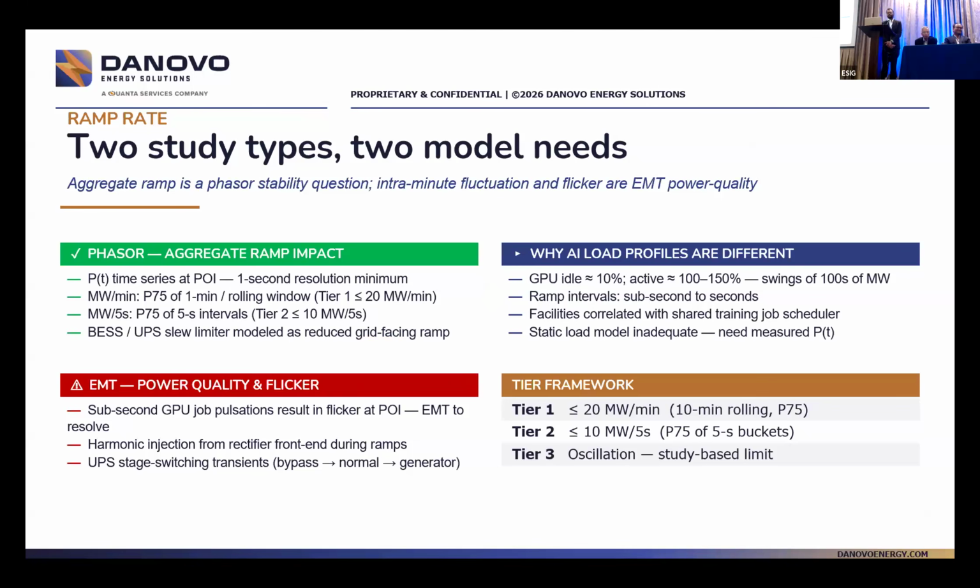Okay, so over here, the Phasor requirement, I said you can study things. A lot of it maybe even doesn't need Phasor modeling. There was this unique case where we were looking at the behavior of EV load because they were all supposed to start charging at 1 in the morning, and you could see the impact of that and what that does to the regulating reserves and how you exceed your area control error and you start sending the signals to generators outside your balancing authority to ask them to participate in governor response.